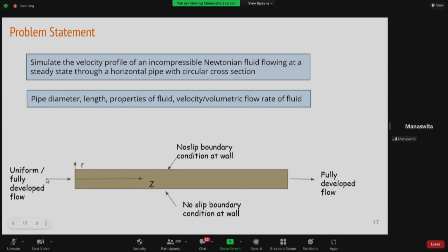And we have written the boundary condition at the inlet and the outlet. At the inlet, we have said, if you want to get an analytical solution, because unless we simplify the equation we cannot get an analytical solution, so for analytical solution, at the inlet also, we assume that it is fully developed flow. So what does fully developed flow mean?